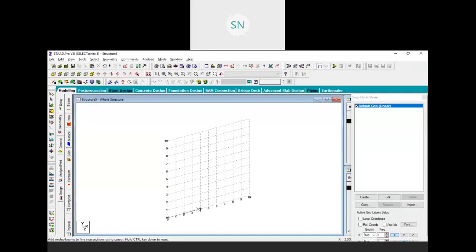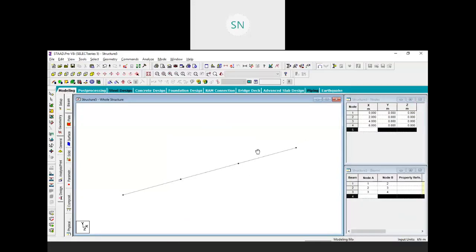So at every 2 meter I am creating 3 beams. So these are the 3 beams in the beginning, right? And we want a circular water tank, but we cannot create a circular water tank, right? It always becomes a polygonal water tank. So let's divide our water tank into 18 divisions. So every division will be at a 20-degree angle, right? 360 by 18, so 20 degree.